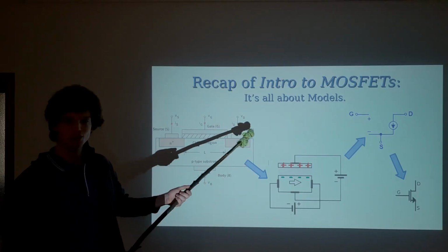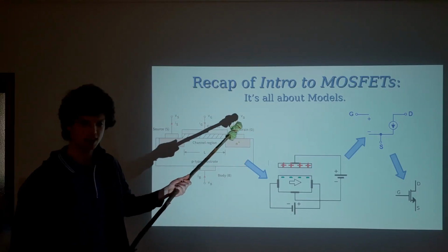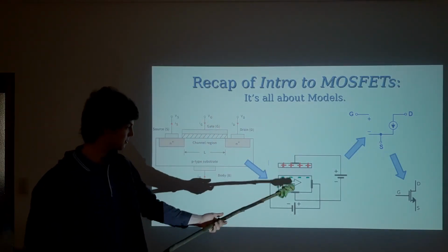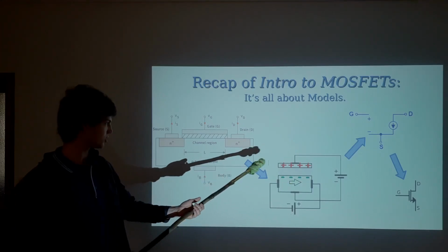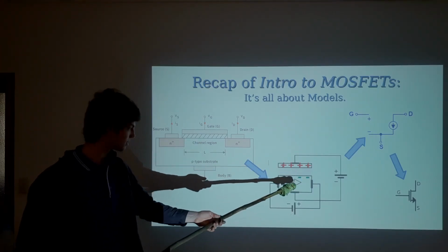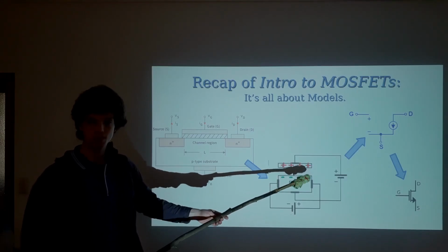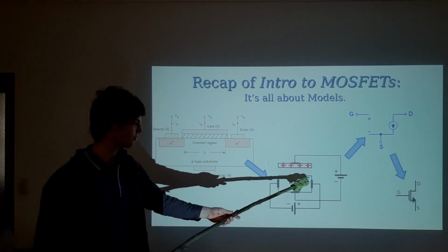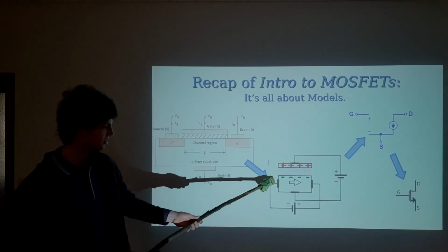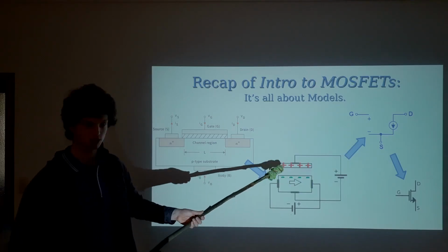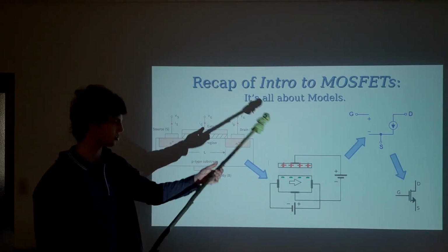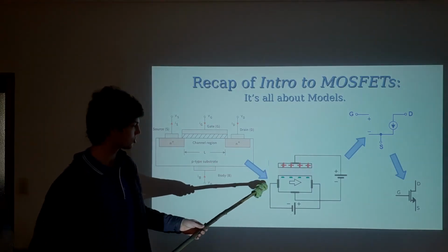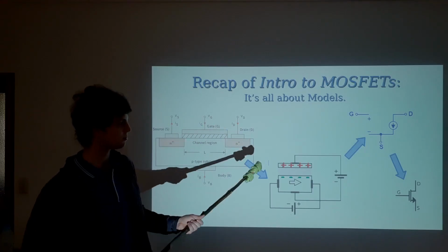We can model the central part of this metal oxide field effect transistor essentially like a capacitor. So we have charges that build up on the gate, and that draws in negative charges from the substrate into the channel region. When we have enough charges built up in the channel region, we have enough mobile charge carriers, and a current can then flow, because we put a bias, a positive to negative voltage, sideways across this channel region between the drain and the source. So this is like a voltage controlled resistor. The voltage on the gate controls the resistance between the drain and the source.